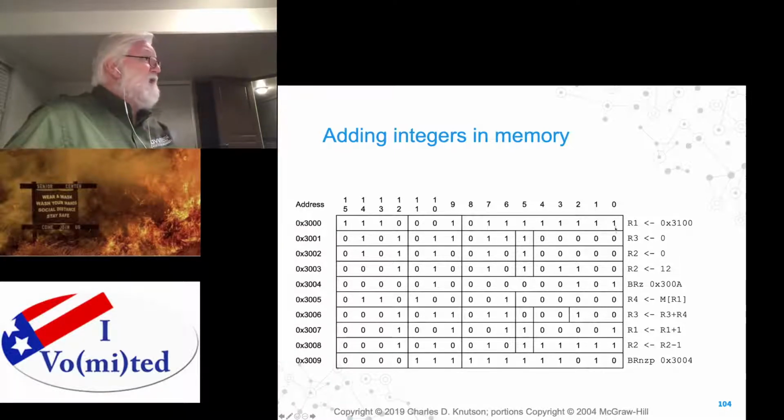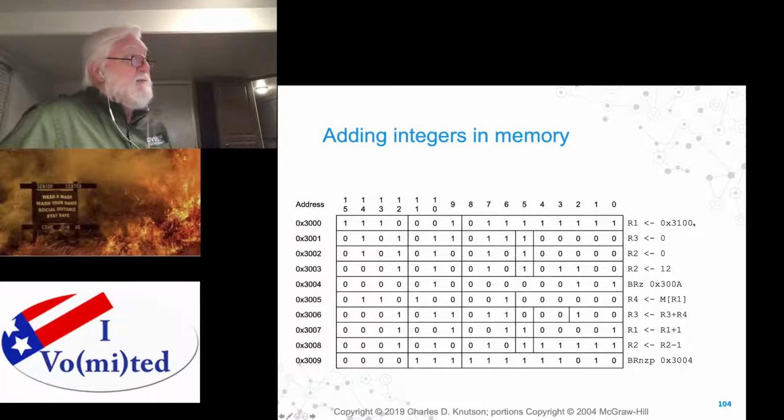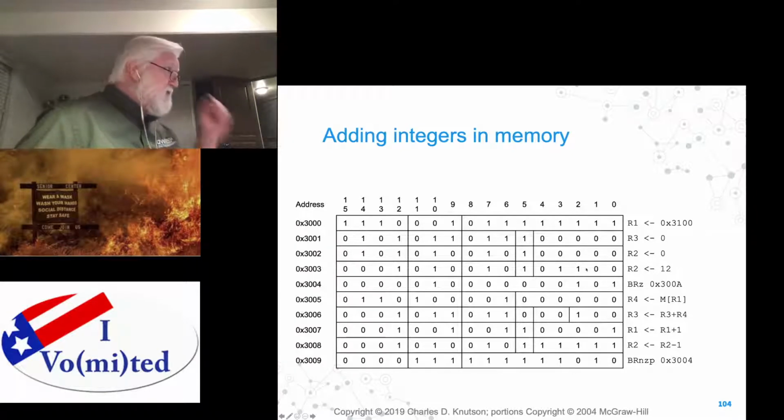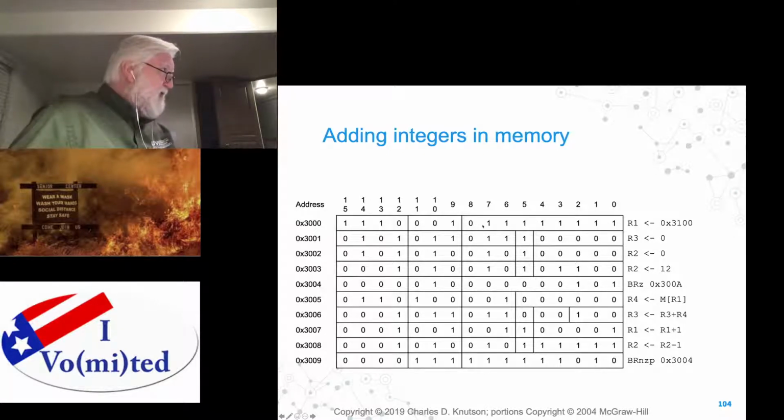If you look at them, do the math, right? It's basically, it's 100, right? You got these 4 become 0, then these 4 become 0, and there's a 1 that spills over. And so you're adding that positive number to 3001, and you get 3100. Okay? So that is, essentially, you're adding FF to 3001. And you're adding FF, which is this value right here. Everyone buying? 4 bits for an F, 4 more bits for an F. It's a positive number. Okay, so we take that value, 3100, we put it into R1.